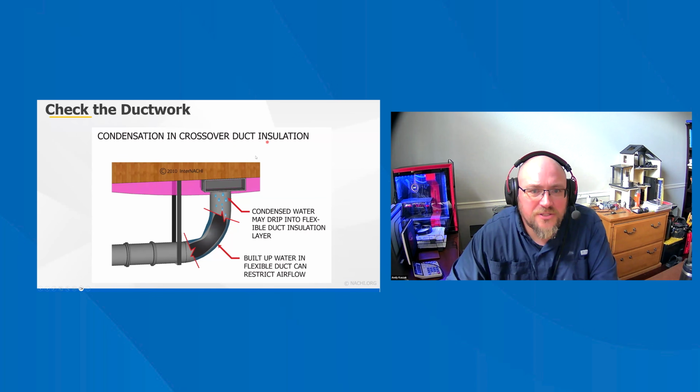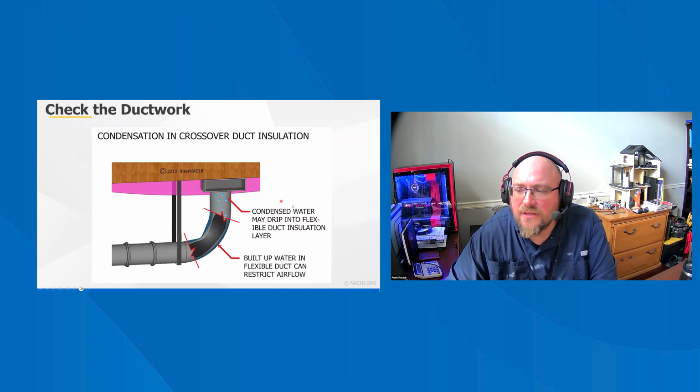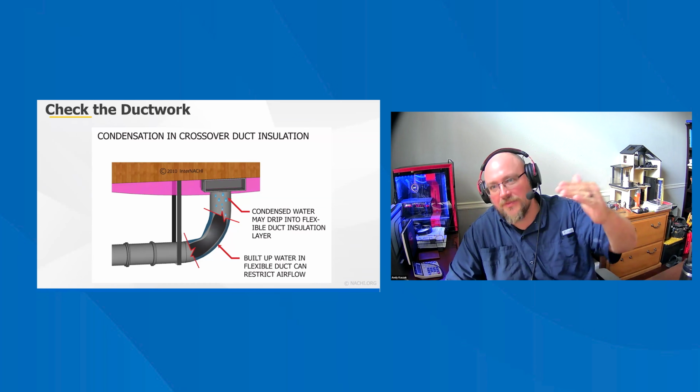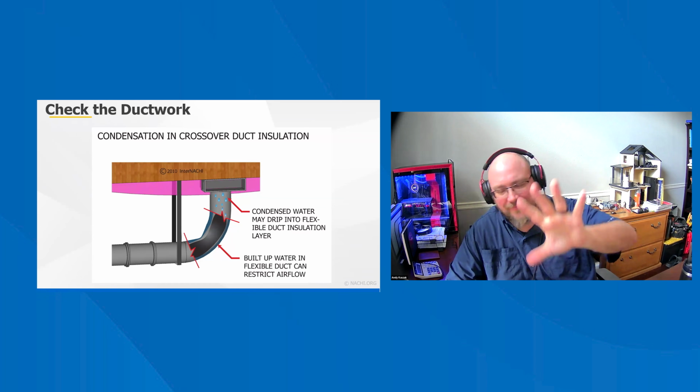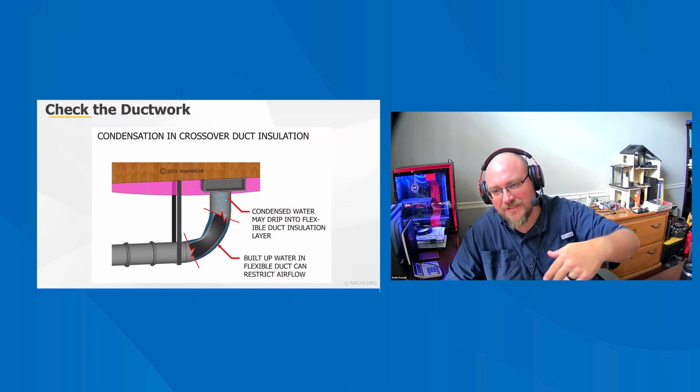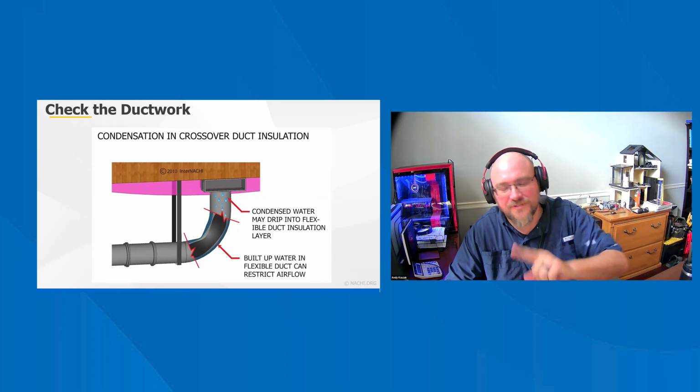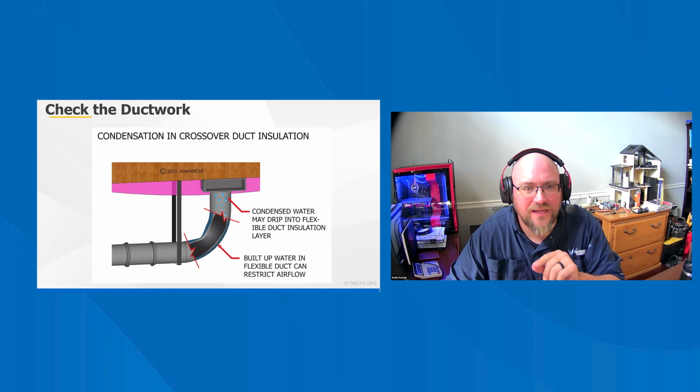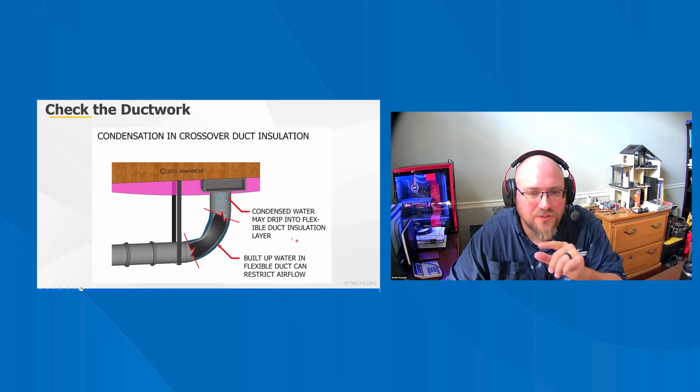So condensation and crossover duct insulation. So facing downward, is it upside down? Yes. The paper should always be on the warm side, and there's a really good picture I have at the end of this class that shows you why that's important. So yes, we'll talk about that here in a second or at the very end. Thank you, Robert. Yeah, we'll address that.